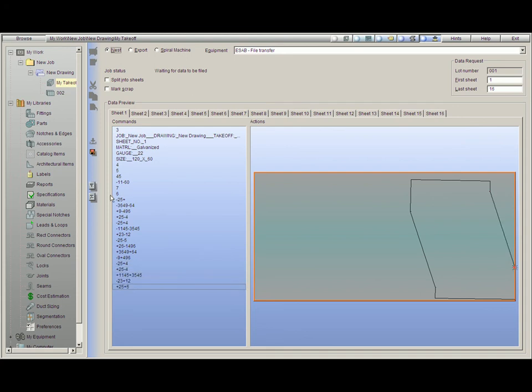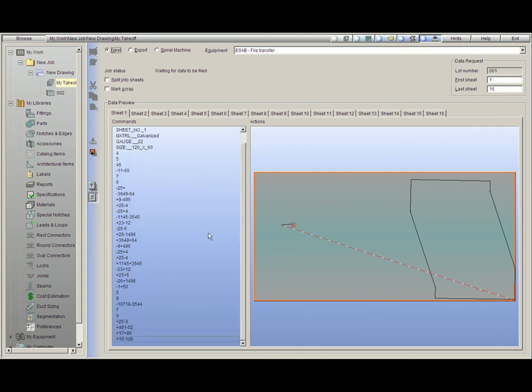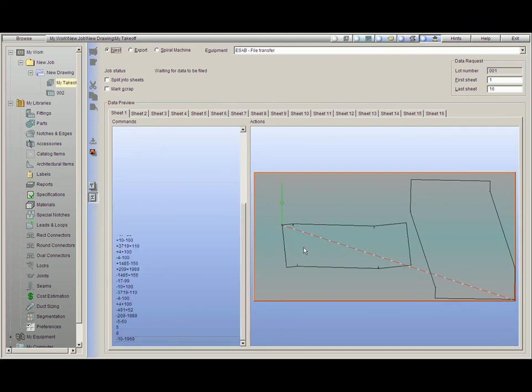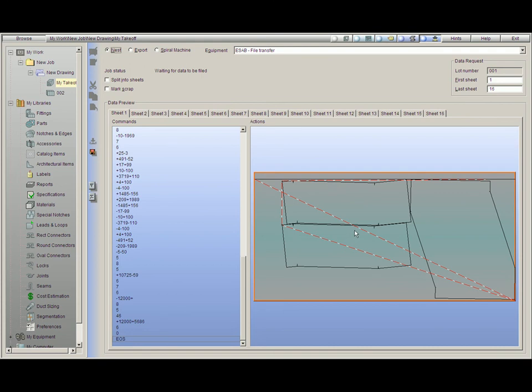If you'd like just to set it on automated and just hit trace the selected sheet and watch the whole sheet cut, just press the trace the selected sheet button once, and now you're going to see PractiCAM cut each piece. You can watch the entire cut path from start to finish. The red lines here of course are the free travel for when your cutter is not cutting. That'll conclude our section on fabrication.